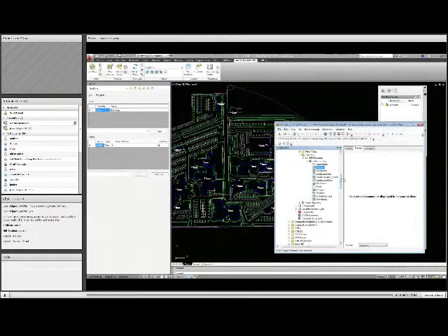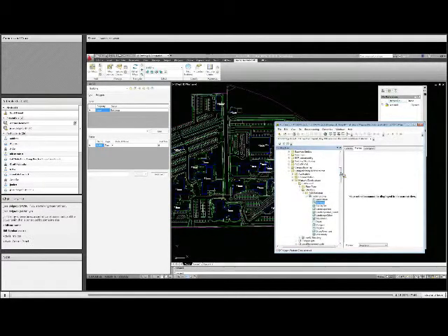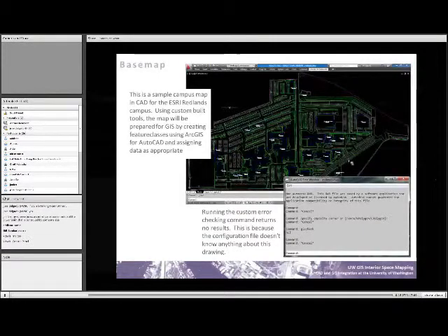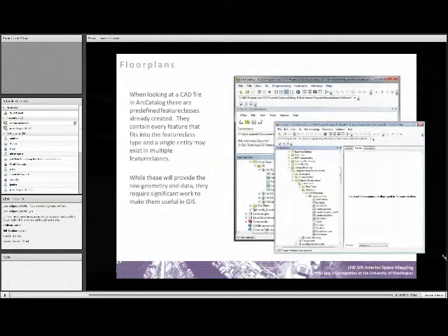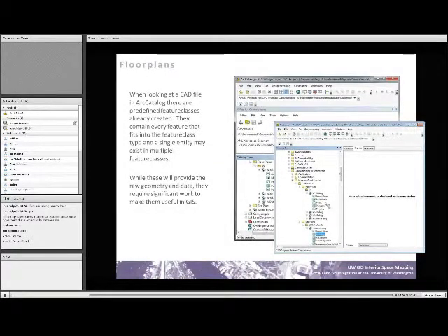It's nice having the square footage in CAD because we actually use CAD for quite a few things, but keeping the square footage text updated is really not very feasible. So I have a command that will go through and attempt to link all the room numbers with all the polylines, and it'll create the square footage as an attribute, as a field, which also gives us our same link to the polyline. And from here, I can do my error checking and it found problems. It actually found quite a few problems. So there's a bunch of rooms. Oh, and I think it didn't pick up some of my room number blocks.